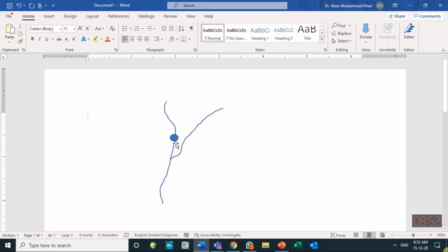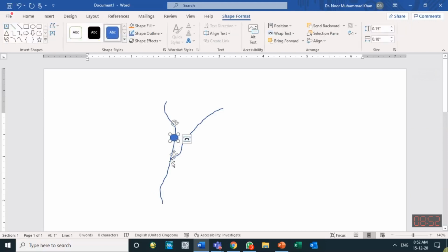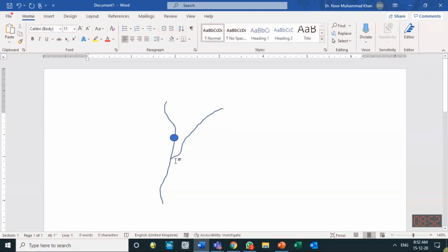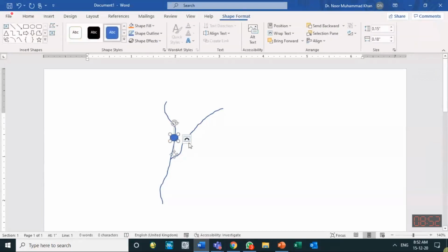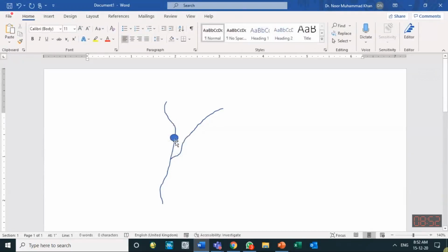So we should avoid this location of the stream gauging station from such location where a downstream tributary can affect the water level of the stream gauge on the upstream side. So if it is the condition, why should we avoid this? Because usually we measure the discharge by first estimating the stage.